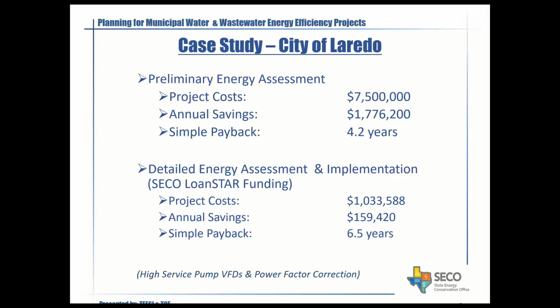Let me jump in here. It was a real interesting case where Laredo's minimum size high service pump was too much flow during their low usage period of the evening, which is like from midnight to 4 a.m. So it was filling up the water tank and overflowing. And we recommended putting a VFD on it so that their minimum size pump can pump at 50% of its max capacity. They were able to do that, and that completely solved the problem real quick. They solved their water leak and saved money.